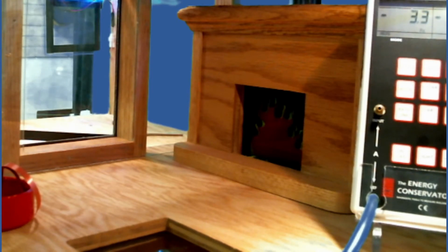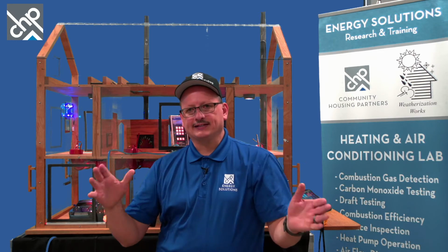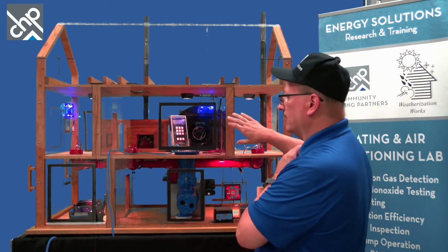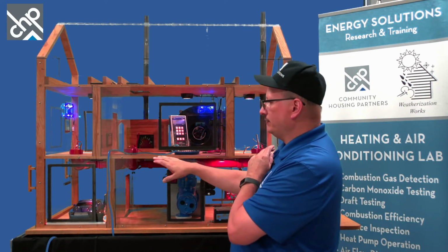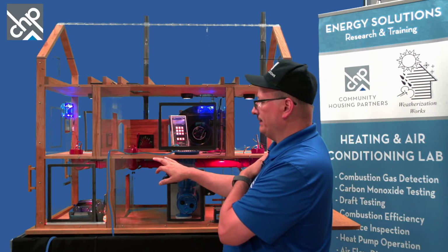And part of the reason it was probably better, with the door open from the basement to the CAZ, was that when you opened that up to that area with the dryer, it was a huge bit of volume. So basically, the exhaust fan didn't make it worse, but the excess volume in that room made things better. So right now, the worst case is with the bedroom door closed. We smoked this door, smoke went under, so we opened it. We smoked this door to the basement. It didn't go under, so we left it closed.